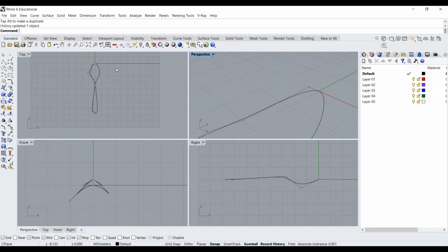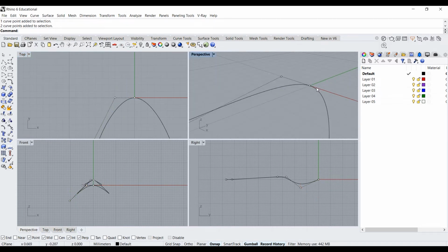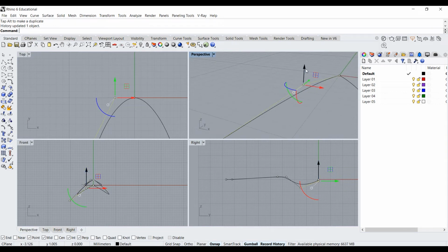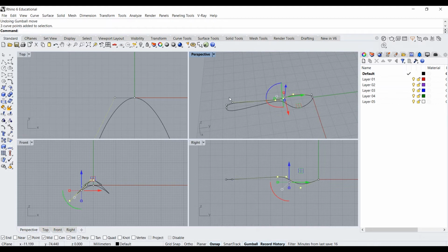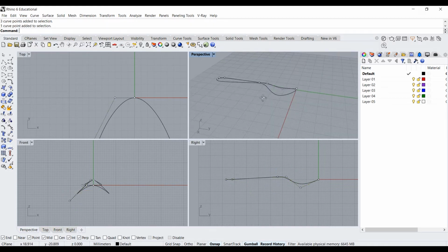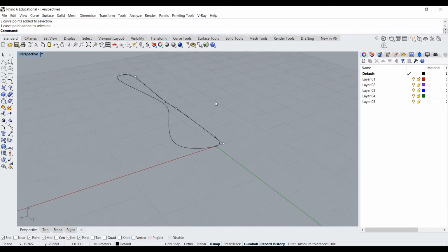Again here, just how we made sure that these points at the top were parallel, we need to make sure they're parallel in 3 dimensions as well, so we don't drag that up or down, because that similarly gives us a horrible pinched drawing or object. So we're only really editing the middle points here in our scene. Okay, that's looking good. I'm quite happy with that. And from here, we can now start to turn this into a surface.